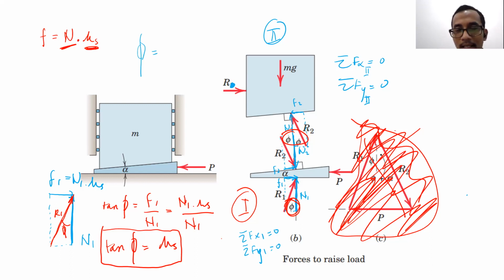If there is no statement about moving, which means the problem is just as it is, then you have to assume that everything started from a stationary position. But if it is stated there that the object is already moving, then in that case you have to use mu k.